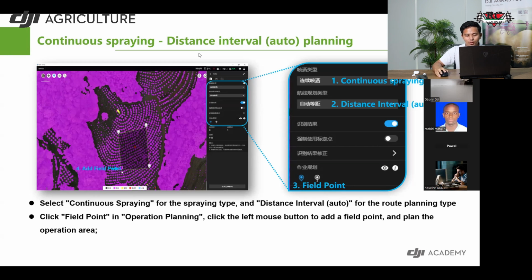Yes, this is the second way. The first way, many people think RTK must be put at the same place. Actually, from my experience, if you use the fixed points, you don't need to put it at the same place. Imagine we must spray 100 hectares from one RTK, from one spot. But when we do the job, we will need to move, from more than 2 or 3 spots. That's because of our aggressive zone, we need to maintain the line outside at all times for safety reasons. So we may require more takeoff points. So unnecessarily, you need to put the same exact point for the RTK base station. For that reason, I always suggest using absolute calibration points.